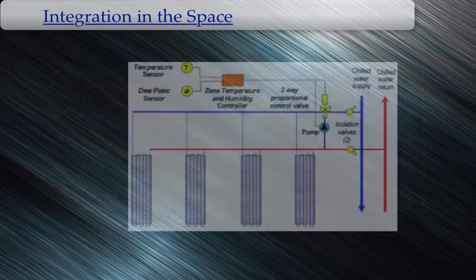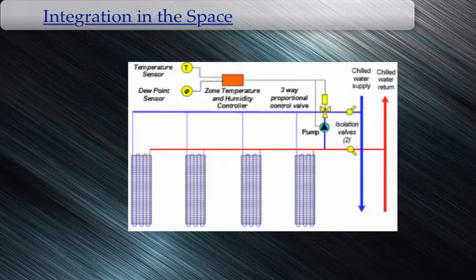Another positive attribute that is associated with active chill beams is the space that you save on the required air duct layout. Since water is much more efficient at transferring heat than air is, the only air ducting you would need would be for ventilation purposes. This would make the installation process much simpler and allow more freedom for other aspects of design.